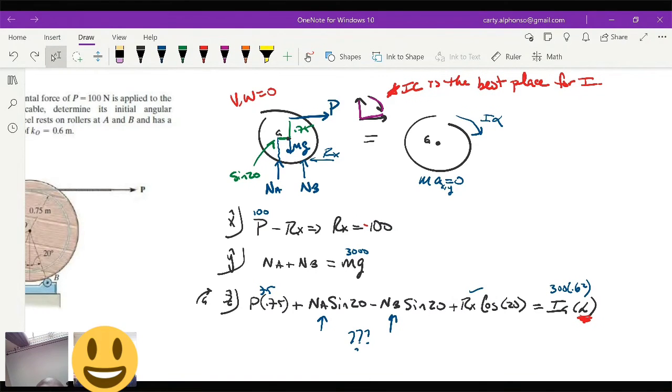So what I'm thinking is these guys are forces. Yeah, they're perfectly balancing the mass. And because they have the same geometry, it's a little triangle. So this would be the center of mass. This is in A and this is in B. And that's an isosceles triangle, which means that their components to balance the mass should be equal. They're balanced. So I'm actually willing to believe that they're both half, which means that it's just going to be N, which is equal to 3,000, which means that these two would actually cancel out on each other.